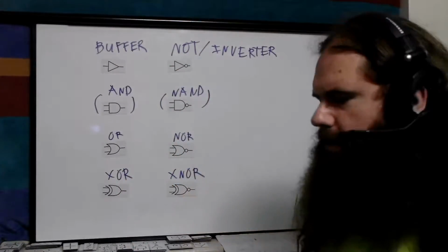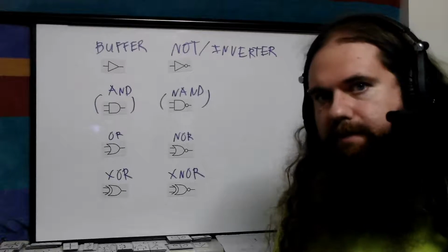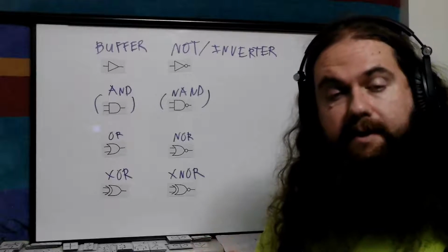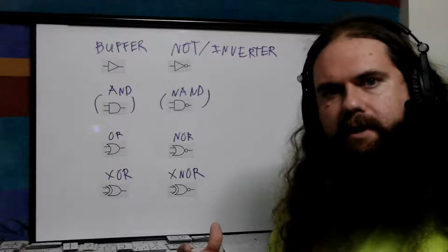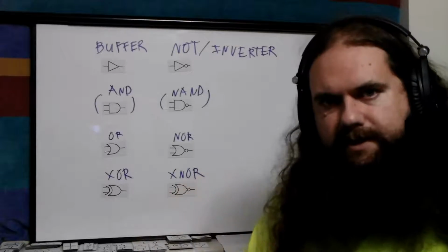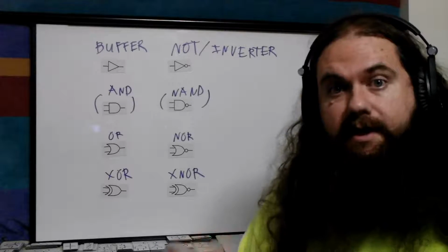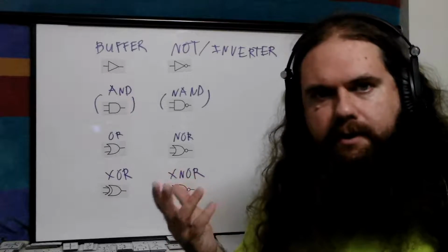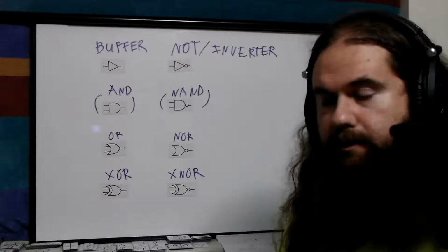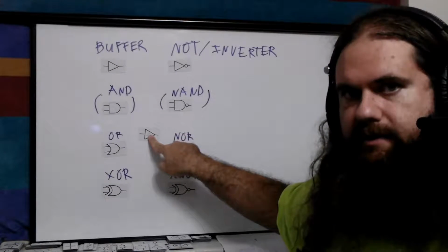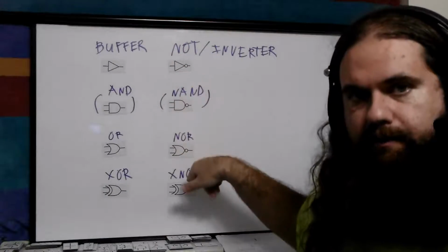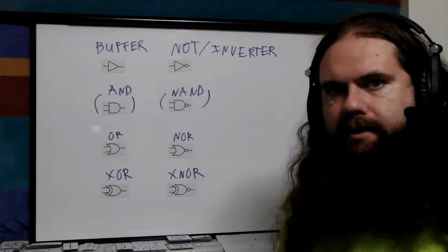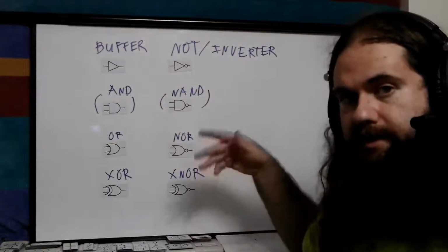The bubble means inverted. The bubble is used in certain other cases, such as a Schmitt trigger, sometimes. That's an inconsistency because some people have a circuit diagram that reflects how the circuit works, and some people have it reflect logically how it works rather than physically. The actual function rather than the construction, because you can get the same function from different constructions. And as usual, people couldn't agree, and there's a multitude of different ones in use. This symbol here, you see the little thing in there? It's called a hysteresis, and it goes different ways even. Pay attention to the bubble on these 4 symbols only. They are consistent. Everywhere else you see the bubble, try your luck. But here, in logic, in Boolean operations, the bubble means invert.